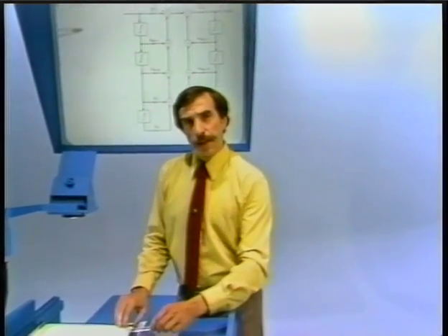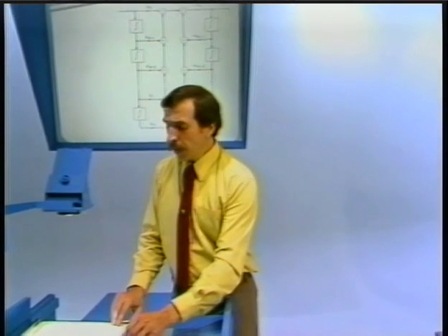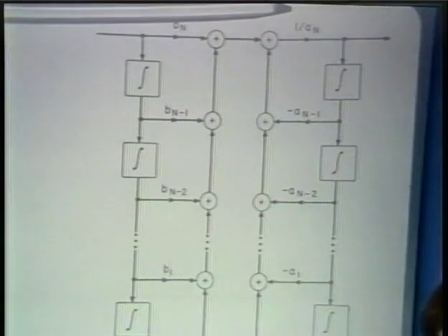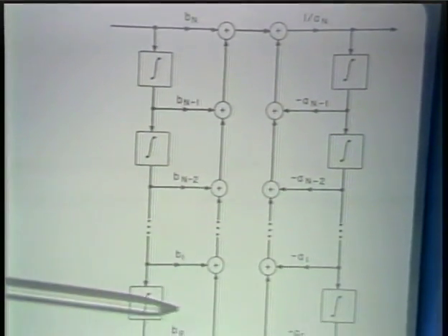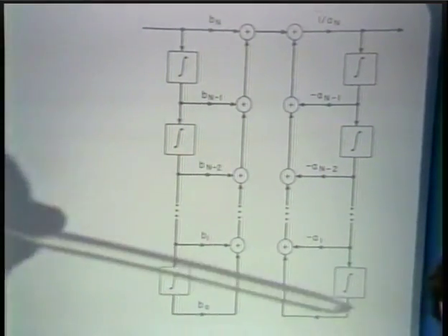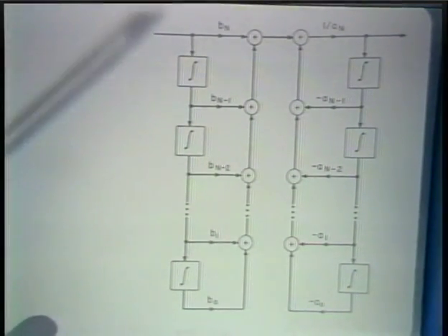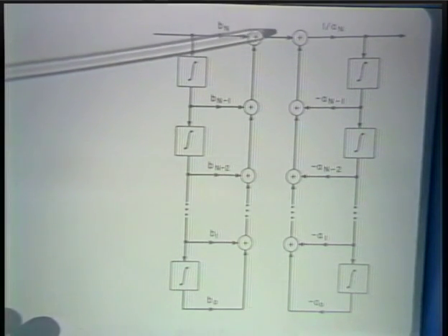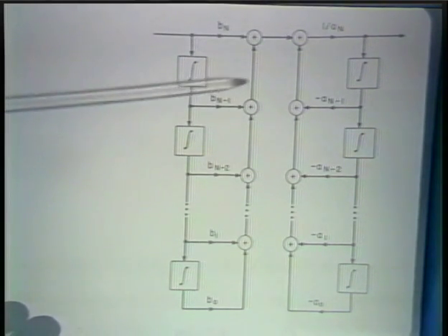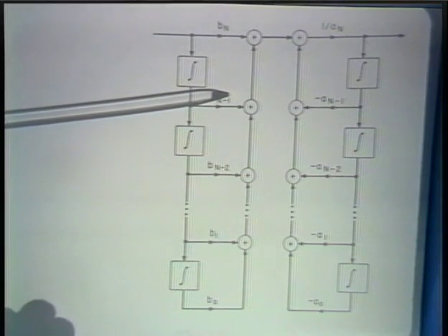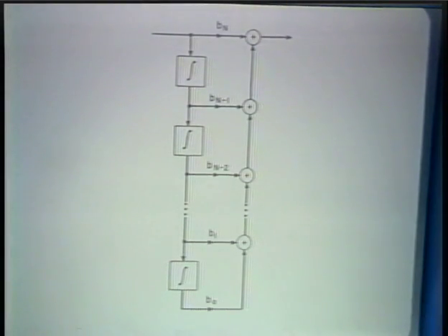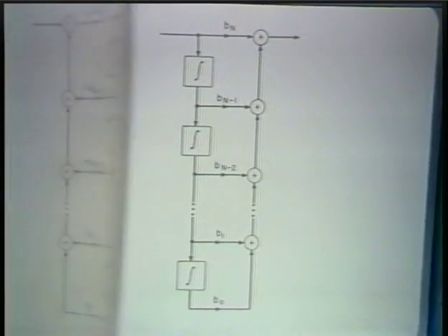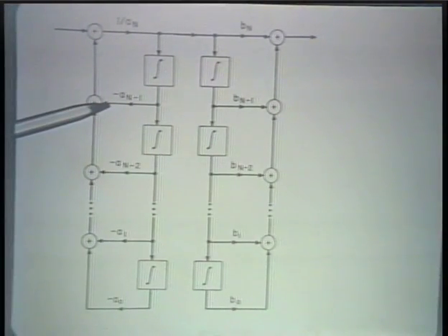If we take the general differential equation and integrate it a sufficient number of times to convert it to an integral equation, we would then have this cascade of systems. And again, if we assume initial rest, so that these are both linear time invariant systems, we can interchange the order in which they're cascaded, namely take the second system and move it to precede the first system.